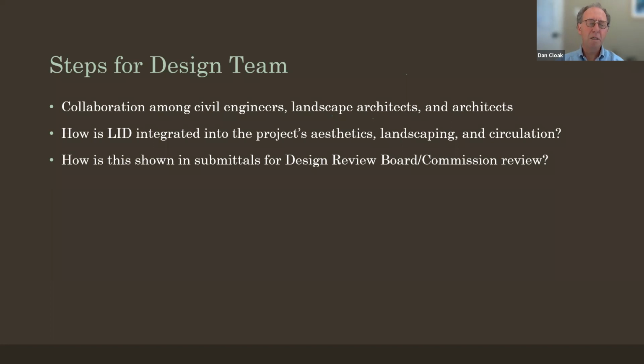Fortunately, you've got the design criteria in chapter 4 of the manual. It's going to tell you basically how these things are going to be engineered. But knowing how they're going to sit there and what elevation the rim of it is going to be, trying to conceive it in 3 dimensions is where you need to get to, I think, before you can complete a rough grading plan.